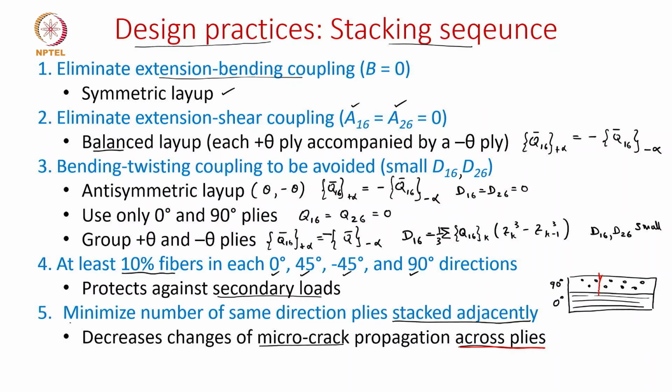It's okay to have two or three plies. As a rule of thumb, one should not exceed a thickness of about 0.8 mm with all the same orientations. Usually this means close to 3 to 4 layers.